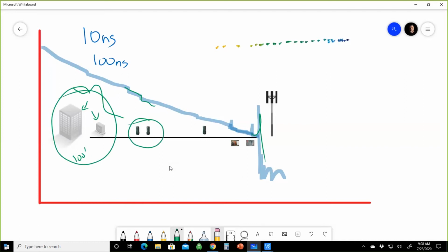So if these two splices here were, say, 15 meters apart, at 10 nanoseconds, I would see it, because at 10 nanoseconds, I got 1 meter resolution. At 100 nanoseconds, I got about 10 meter resolution. So I should be able to still tear them apart. But if I go higher, 275 nanoseconds, then it'll just merge it.